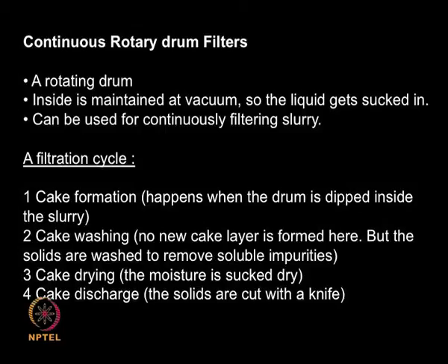Step number 1, cake formation step. This is the time when the drum dips inside the slurry. So the drum is inside the slurry and there is a vacuum applied inside the drum. So the liquid gets sucked inside the drum, and the solids form a cake or are retained on the surface of the drum. This is where the actual filtration takes place. Once the drum comes out of the slurry, there is no new cake being formed. Please remember that once the drum comes out of the slurry, there is no new cake that is formed,